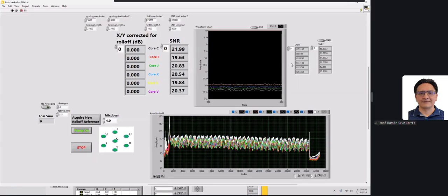Another piece of testing that we do is the kinematic mount testing. Given a single sensor sitting in a mount in a puck, you pick it up and put it back a lot of times and make sure that the position you end up with is exactly the same, or close to exactly the same every time, because that's a requirement of what the kinematic mount is designed for. That's another set of testing that Megan drives and I just support.